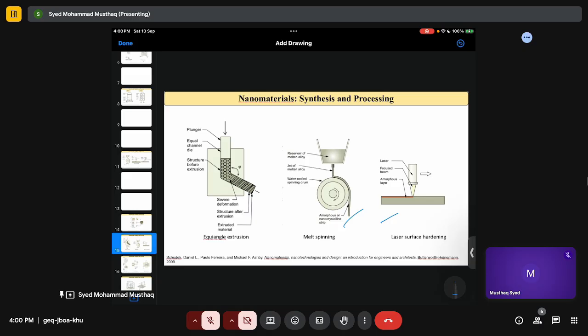Whenever you have, let's say, 1 mm by 1 mm, and you start deforming and stretching it, at some point it may become 50 micrometers, and this length will be increased many times, maybe 1 meter, and then again if you start stretching, this thickness may become nanometers. So that's what we are doing. We are making sure that grains have 1 nanometer in them.